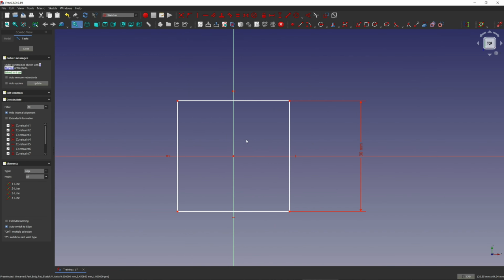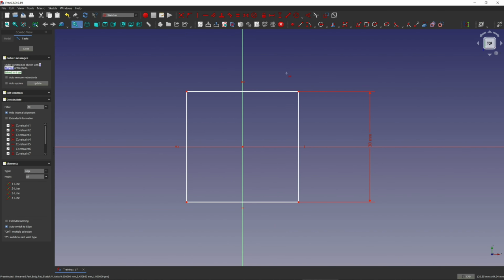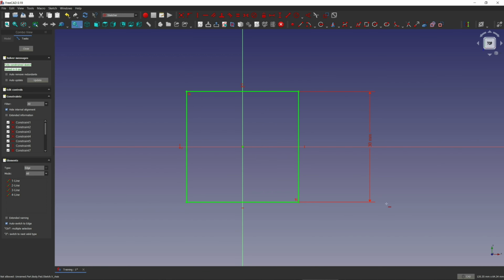By reducing the number of constraints, we're reducing the complexity and making it easier to work with. And I think that's something else that's really important as well. On the outside of every one of these edges, there's a tiny little red line. That is a vertical or a horizontal constraint. If we didn't have those, it would be able to twist and move and do all sorts of crazy stuff.